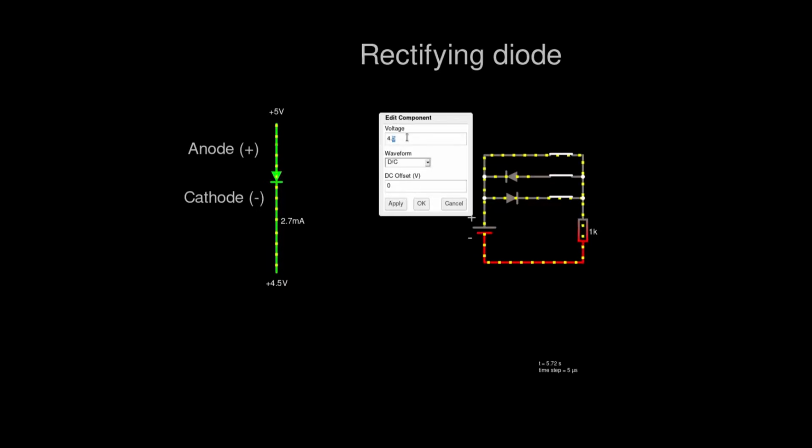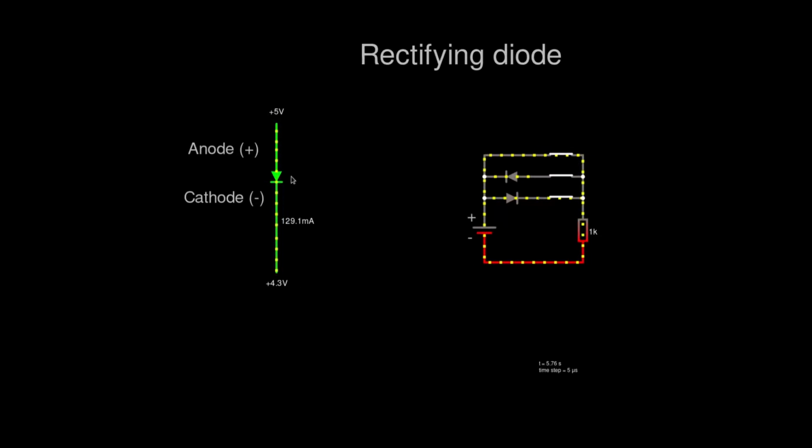And now to the magic number, 4.3 volts. That equals a 0.7 volt difference between the potentials, and that is classically the default value for the diode. It should be forward biased 0.7 volts. For different diodes it's different, to get maybe a different current passing through, etc. But 0.7 volts is the place we can begin with.